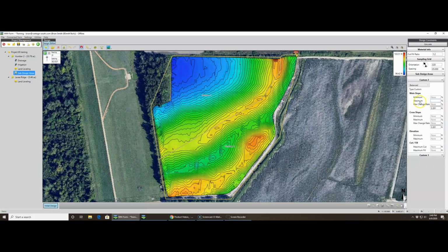Now this changes to minimum. So here we'll need a minus 0.15. Okay, 1 over 100. And the cross slope is the same now as it is in custom 1. Negative 1.5, positive 1.5. So cross slope, negative 0.15, 1/10 by 1/10, 1 over 300. Again, the elevation, cut, fill, min, max stuff, I'm going to leave all blank. I'm not going to worry about our pad design, pad, export dirt in this video.